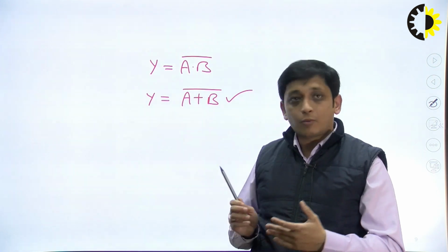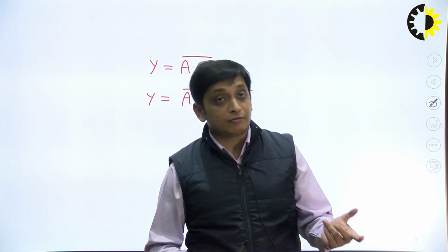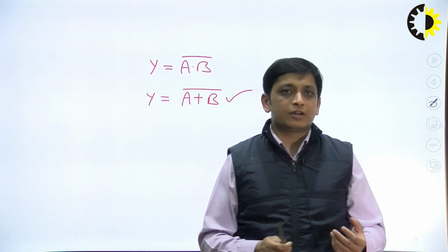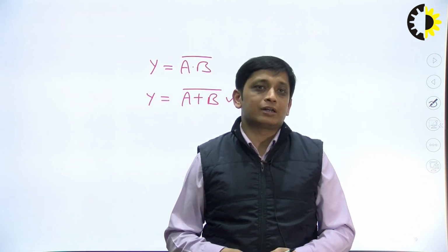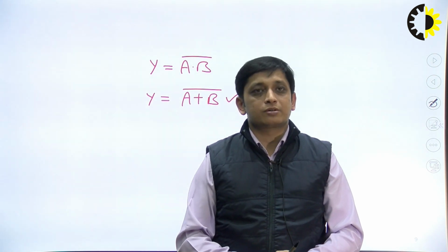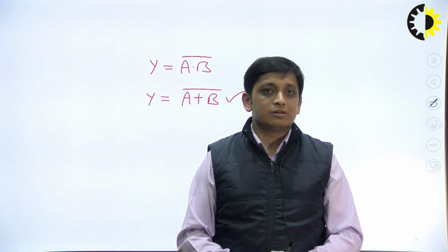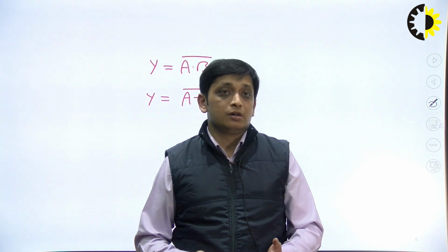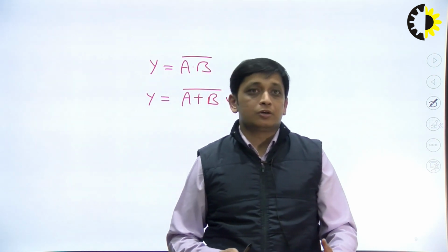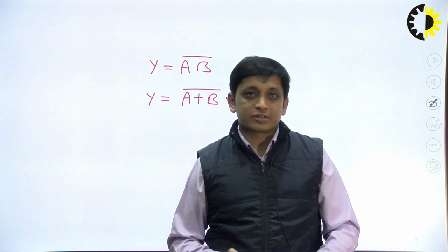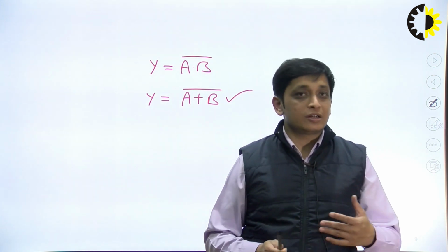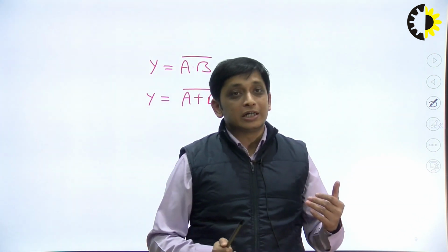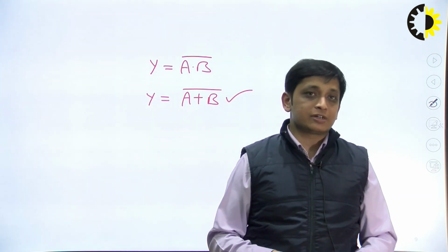Fine. So these concepts are very important because CMOS is very important, because at the start of the class, I discussed the advantages of CMOS. One advantage is that the steady-state power dissipation is very, very low, negligible. That is one of the biggest advantages of CMOS. That's why most ICs are based on CMOS. Also, the noise margin is very good for CMOS, because its capability to tolerate noise is very good, and it is better than the TTL and ECL logic families. The power consumption is very low in CMOS in comparison with TTL and ECL logic families. That's why we are very much interested in CMOS.